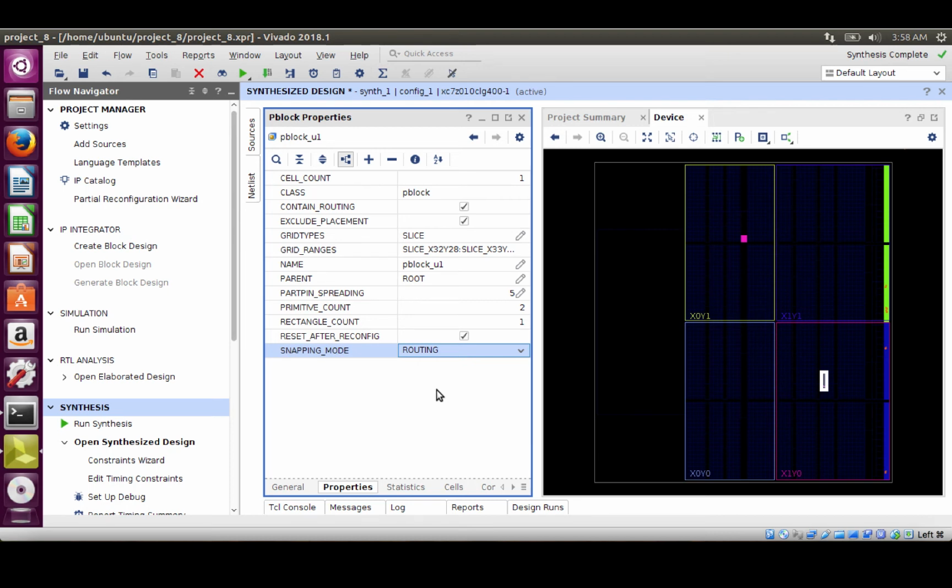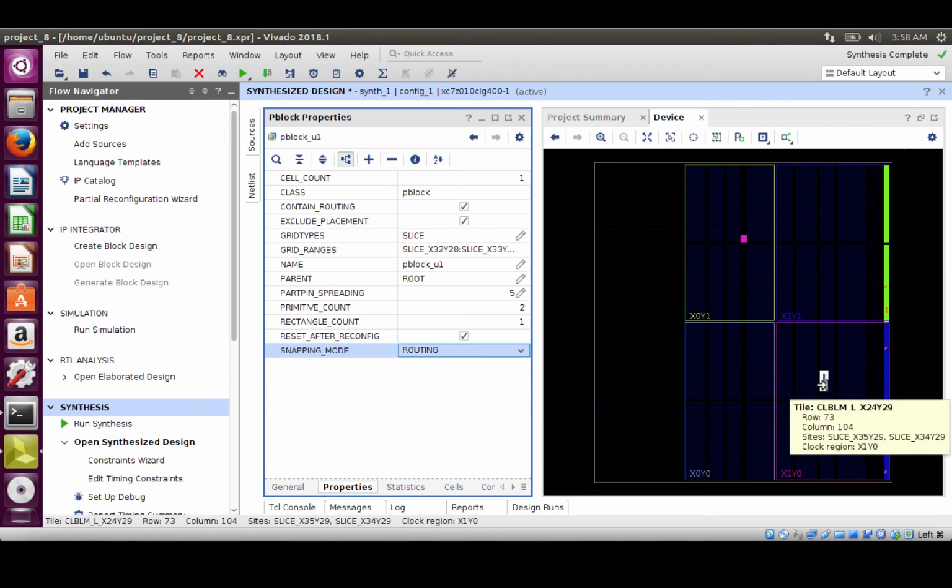For example, if you choose your P block edge on the vertical edge between two interconnects, loading mode will not change it, but it prohibits the placer from placing CLBs next to the edge, and that is very good for loading because that part could be used for loading but could not be used for placement.